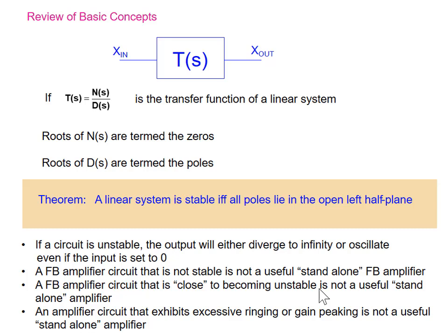Nobody's ever built a circuit with a pole on the imaginary axis, and never will. You build a circuit, and the pole will be in the left half plane or the right half plane. So do we need to define something that never happens? I won't define what the imaginary axis is, because you'll never put a pole there anyway. You might have a pole that moves across it, but you can't build a circuit where the pole will sit there.